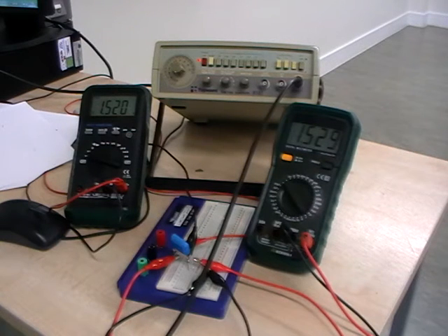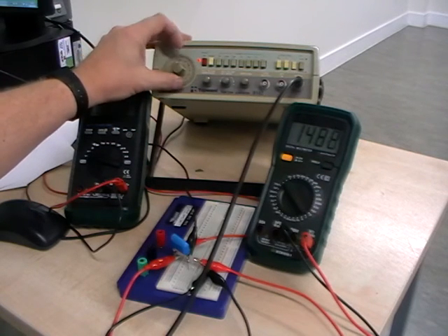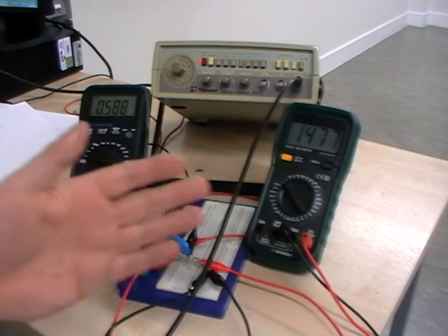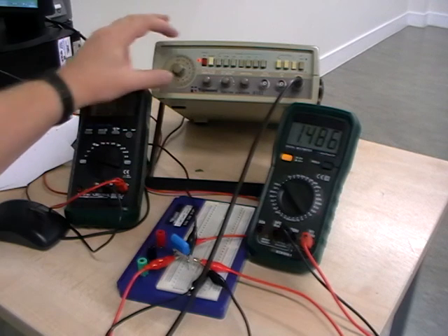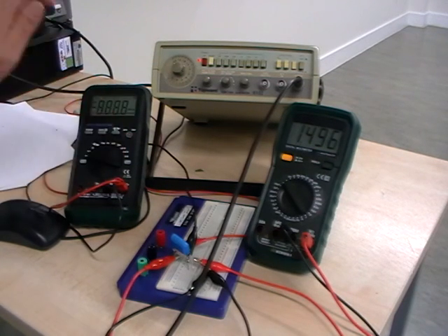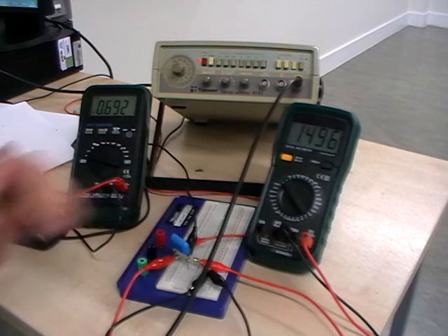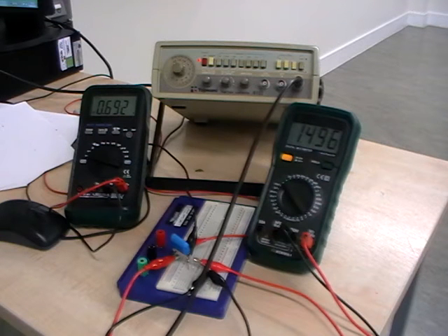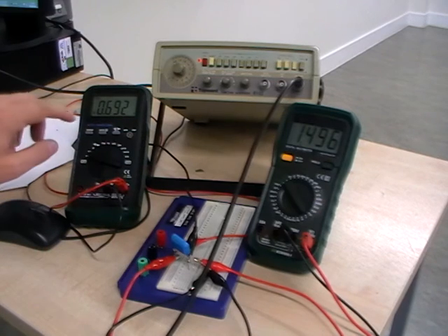Okay, what next? Let's go a little bit crazy and go up to 2 kilohertz, see what happens. And what we find is we've gone a little bit above, I think. And my little meter switches off again. Let's switch it back on. Okay, so we've got about half the voltage now. So that means we've got about 75 ohms across our capacitor, and we've still got 150 ohms across our resistor. That's what we can tell from this voltage distribution, looking at Ohm's law.